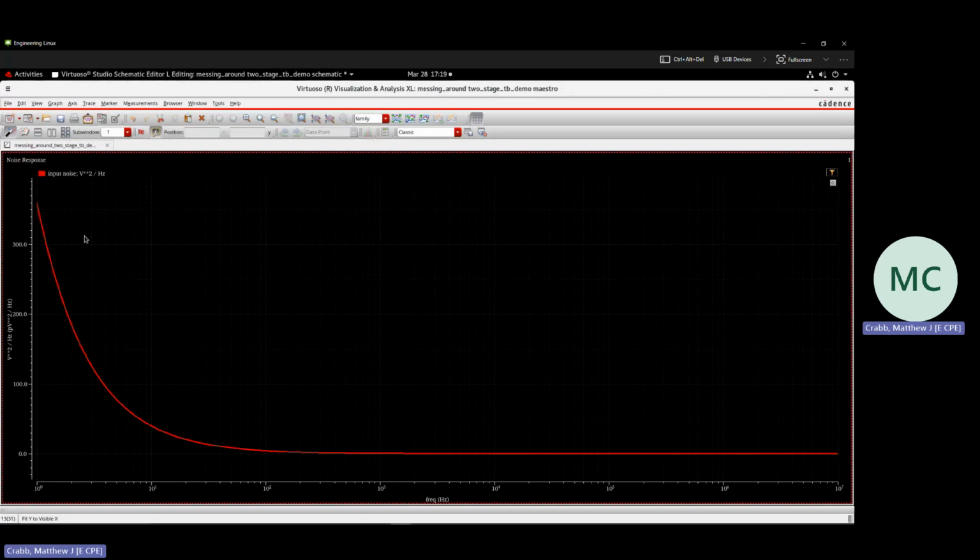And so this plots our power spectral density of the input referred noise, which I think you guys talked about in class, but it's basically at each point here, it's the noise in a 1 hertz bandwidth centered on, so it's the total noise within a 1 hertz bandwidth using like an ideal brick wall bandpass filter, centered around this frequency. And then it sums all that and then puts it there.